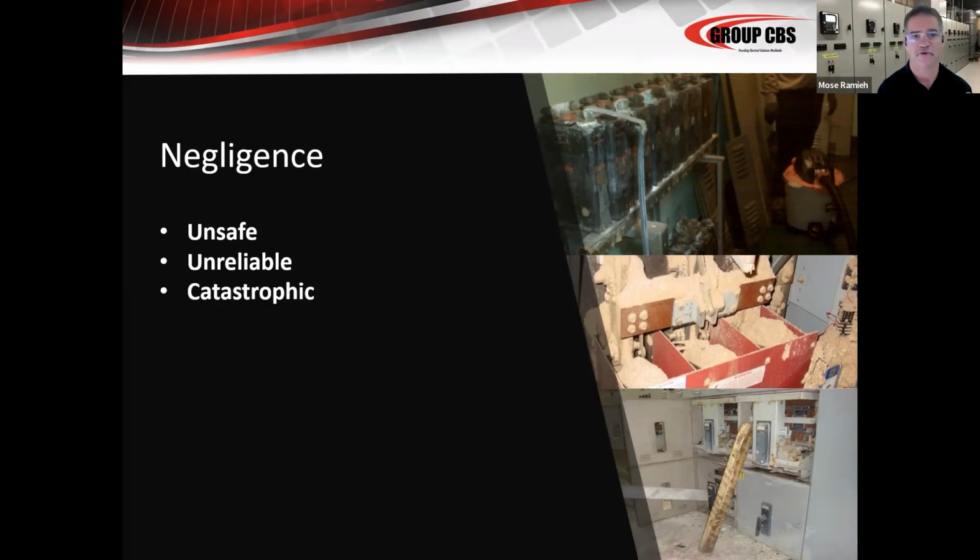The basic numbers bore out that if you don't inspect and test your equipment at 3 to 5 years, which is sort of the interval they've come up with, the probability of, say, a circuit breaker not operating properly is relatively 50-50. That's a 50% chance it will, 50% chance it won't operate properly if it's gone more than 3 to 5 years. So we should stress to everybody that if you are doing routine maintenance every 3 to 5 years, you probably have a pretty good system going.